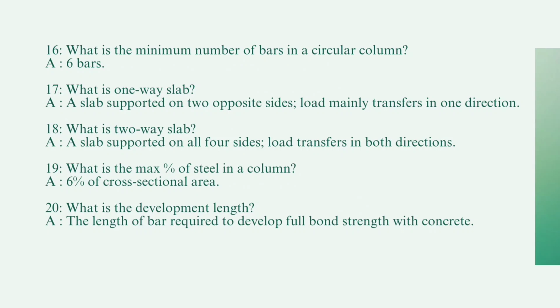Question number 19. What is the maximum percentage of steel in a column? Answer is 6% of cross-sectional area. Now question number 20. What is the development length? The length of the bar required to develop full bond strength with concrete is the development length.